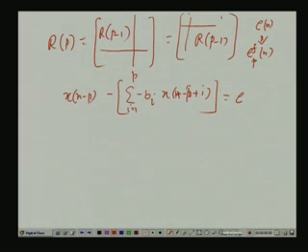Okay. Using that terminology, analogously, this will be the pth order backward prediction error, E p b n. It is n and not n minus p, because this is the convention. We look at the latest sample in this left hand side. The latest sample is when i equals p, you put p here, you still get x n. That is, x n minus p is predicted from p future values. So, the p future values are x n minus p plus 1, x n minus p plus 2, x n minus p plus 3 up to x n. Since n is the current index, the convention is to put n here. Okay. And these are the coefficients.